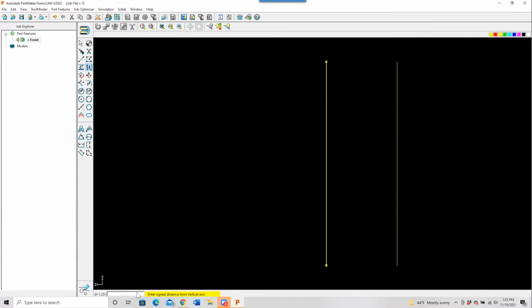In most other CAD systems, if you're working on the left side here, you would have to put in a negative value, or if it was the sub side, you may have to put in a positive value. With positive Z programming, I just put in the number I want, and it's going to show up in the right spot. Okay, so always have positive Z programming checked on, and you're not going to have to worry about any of your Z vectors.